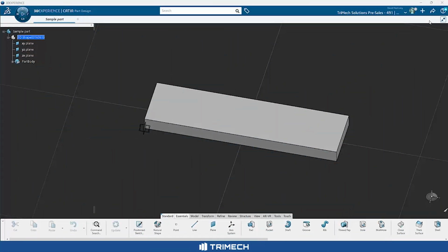Hi everyone. Continuing on our topics of transitioning from Solidworks to 3DEXPERIENCE CATIA, wanted to look at the process for creating what Solidworks users would call a cut extrude, what CATIA is going to call pocket. So just like we'd start off with the pad creation, now we're going to select a similar face that we would want to create our pocket in this case.